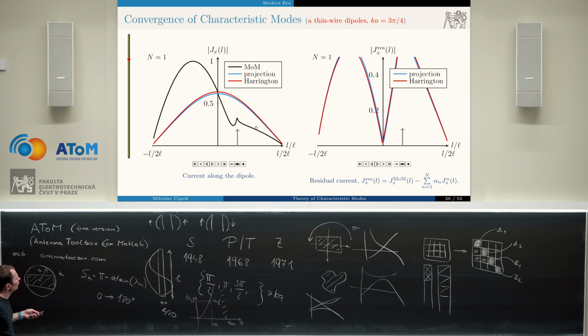And here you can see how to synthesize either shapes or optimal placements of your feeders. Because imagine that for a dipole, the feeder is placed here. Then probably it makes sense that with that feeder, we can very well excite the first mode. We cannot excite the second mode because an excitation sitting here cannot excite this mode, but we can excite the third mode.